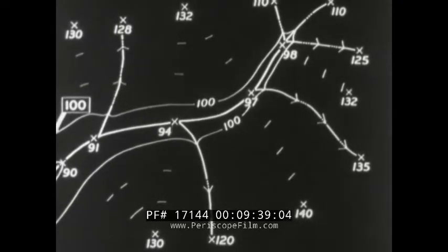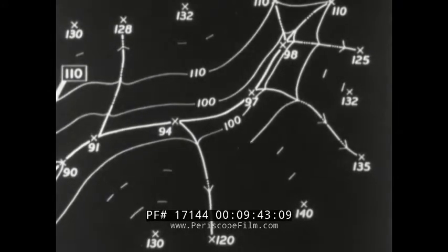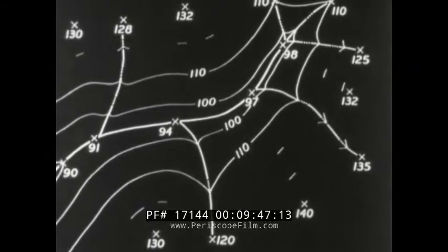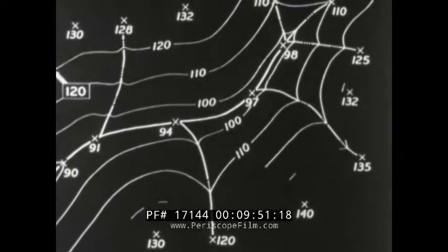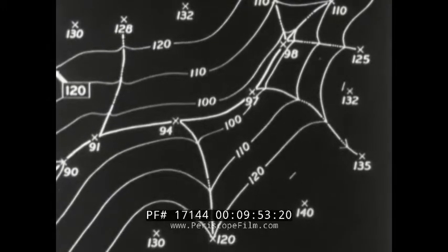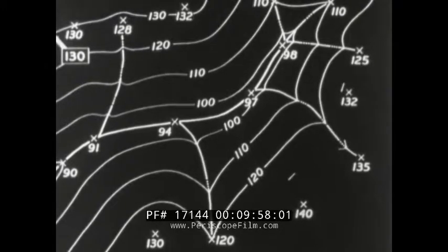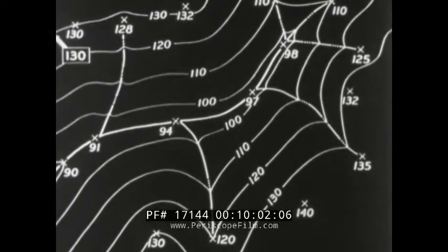Cross the ridges in broad curves and the streams in sharp V's, which gradually change to curves toward the source of the stream or tributary. Insofar as interpolated points will allow, each contour should approximately parallel the ones adjacent to it. Changes are gradual, corresponding to gradual changes in the shape of the ground.